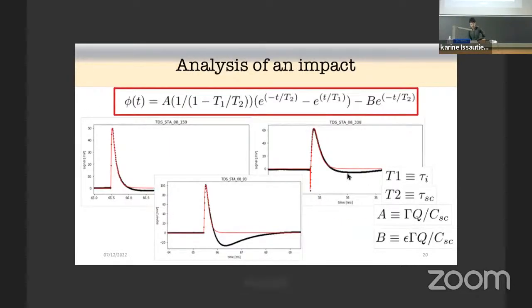Okay, it is really nice because it looks like some kind of inductance is playing a role there. From the engineering point of view, if you have a resistor, inductor, capacitor electric circuit, which is present, of course, in the electronics, then you can have such kind of features. When you applied the inverse transfer function, you actually eliminated part of the overshoot, which clearly implies that part of it is probably due to electronics.